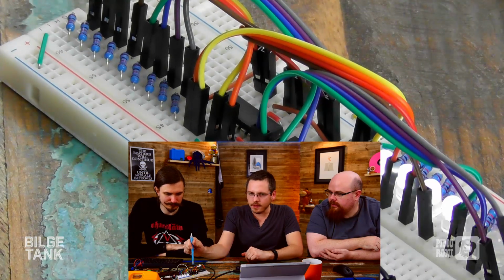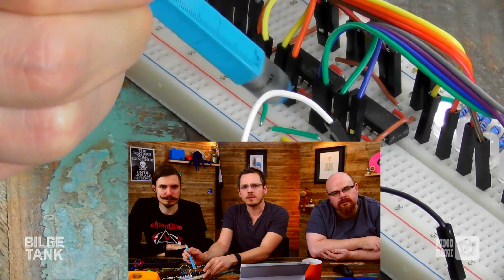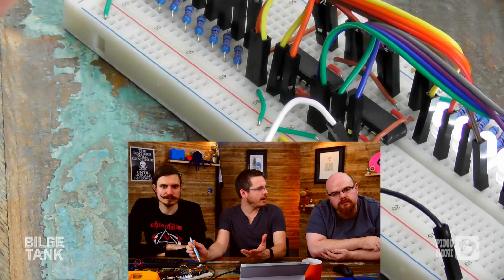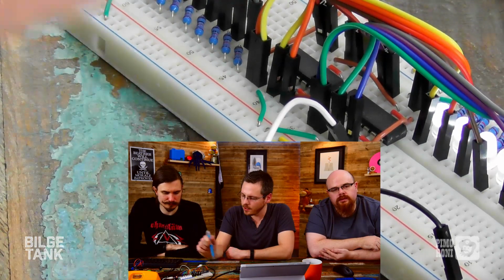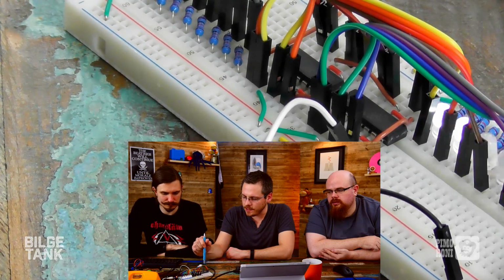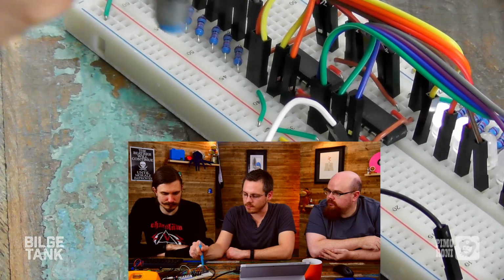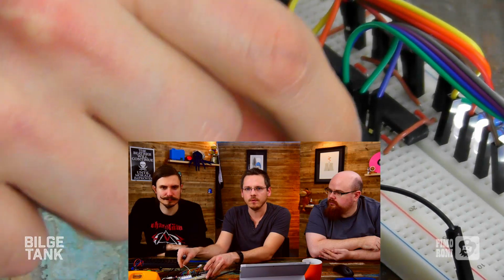Right. And then the 2 chips to the side. We have 2 chips, and they're both quad comparators. So basically, each of those chips contains 4 comparators. So it's a lot more compact than using 8 individual comparators. We just feed one of these reference voltages into each comparator, and then our signal voltage, which we've got coming from a waveform generator,